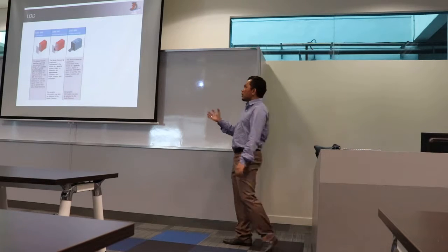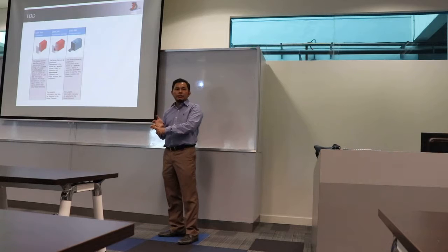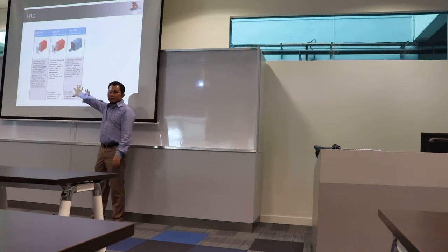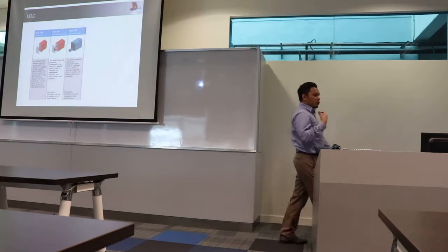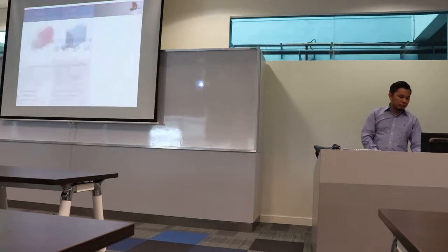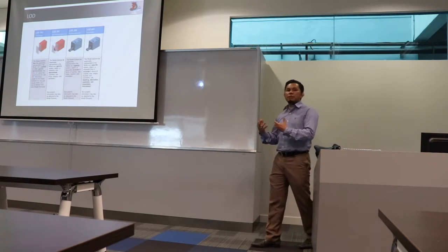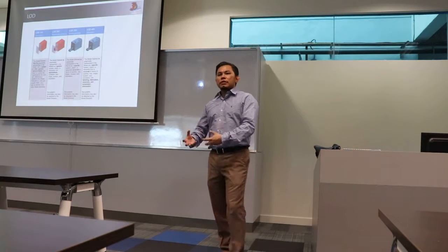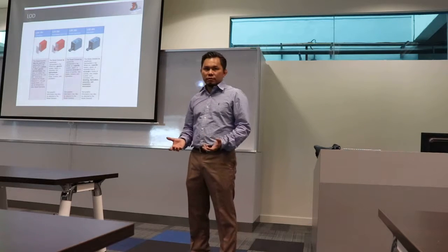Now, if you are a consultant, that means if you are an architect, structural engineer, or mechanical engineer, you would not work beyond LOD 300. Because once you get deeper into construction, this is where we start to look into LOD 400. LOD 400 means information as per what is constructed on site, what you're going to construct. This is shop drawing level.